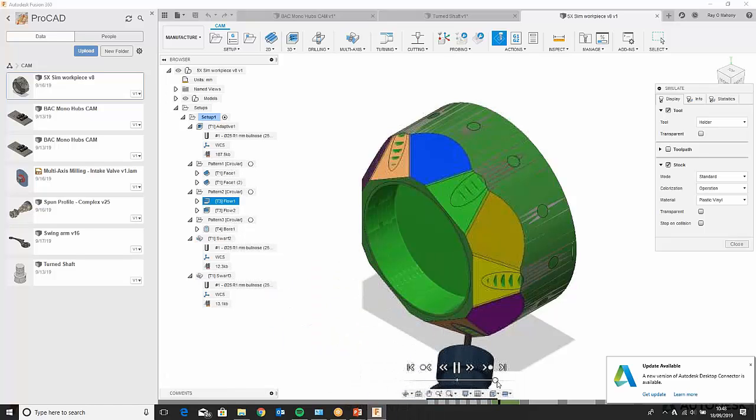So the setup sheet is quite effective. Now we're doing the flow. The flow operation is very much where we can tilt the tool to get into a particular defined area. You can see in this particular face, it's angle number 1. Secondly, we have a lot of fillet work and surface work, and this kind of groove work in there. So this is where our flow processes work quite effectively.